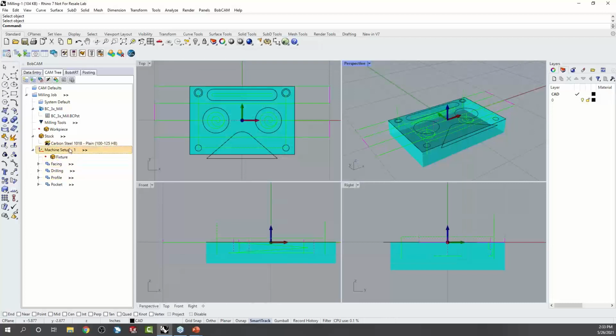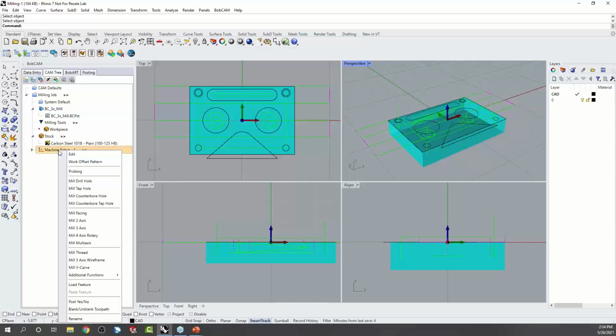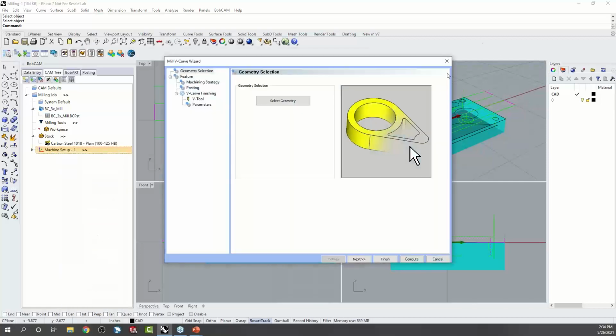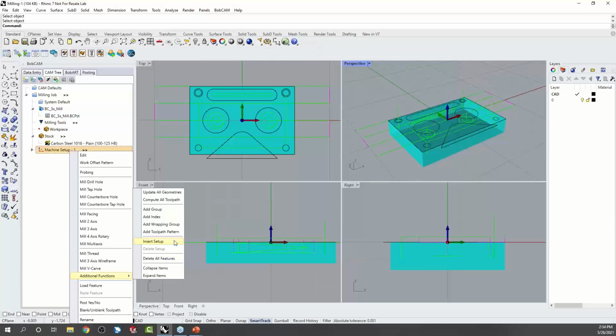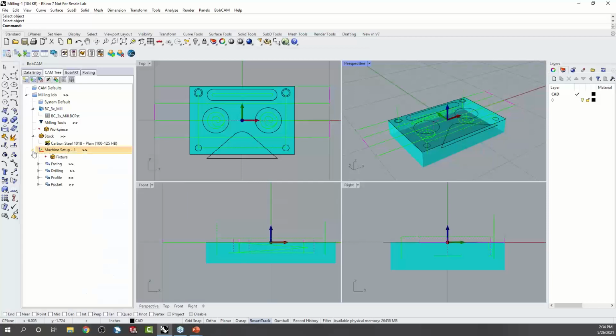Again, your setup here, this is your work offset, your G54. Even though this is a single setup example, you have the ability to load in multiple setups. So you could be in 54, 55, 56. Any orientation, you can pick a setup and choose 3 points to define it, or use a coordinate system and you can define that setup in any orientation on your part.